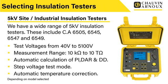And we've got a measurement range anywhere from 10 kilo ohms, so quite low in terms of insulation resistance, all the way up to 10 tera ohms. Really, really high insulation resistances. As I spoke about before, we've got the ability to do the PI, DAR, and dielectric discharge (DD) tests. But these are automatic. They're automatically calculated for you, so you don't have to do this manually.